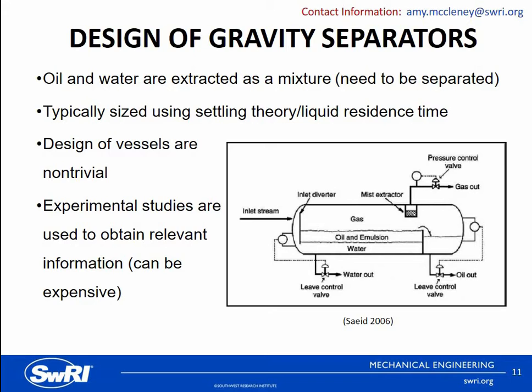Since a multiphase separator is generally the first piece of equipment encountered by the multiphase fluid leaving the field, its efficiency affects the capacity of the entire facility and can present a bottleneck to downstream processing equipment. Proper design of separation equipment is essential to maintain the mechanical integrity of downstream equipment and to prevent operational issues that can be very costly to resolve. Repair, retrofit, and replacement of separation equipment are not always feasible and can easily exceed initial procurement and installation cost.